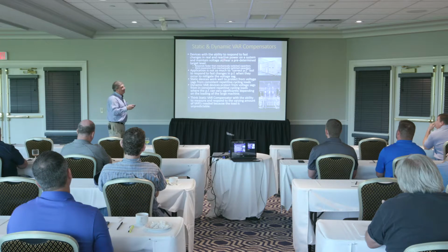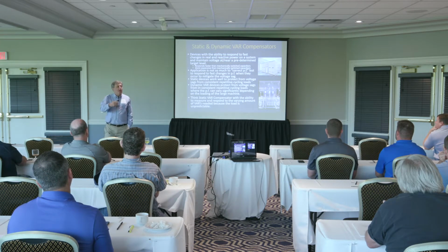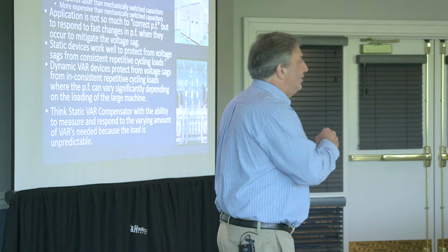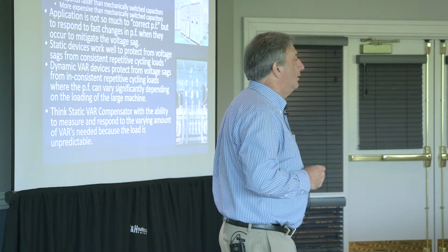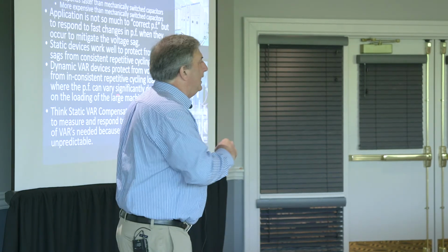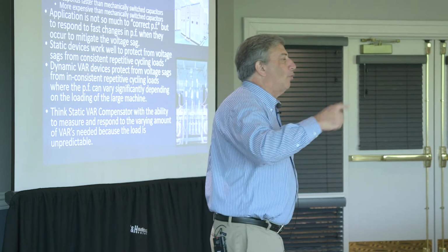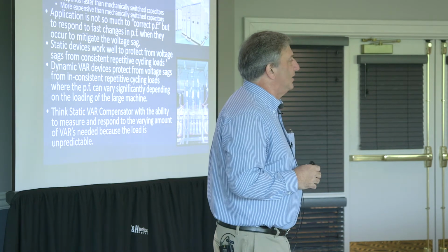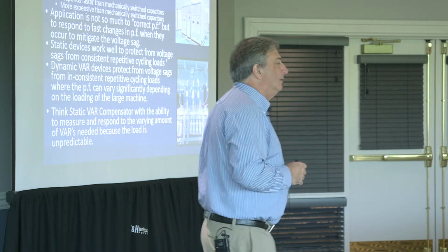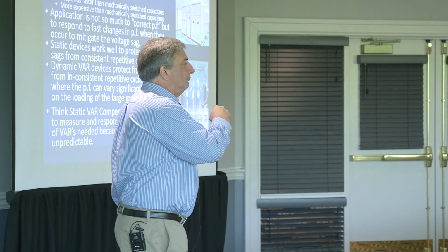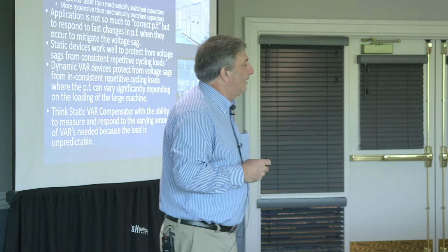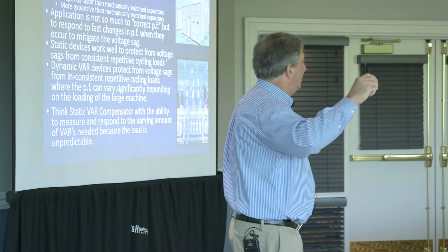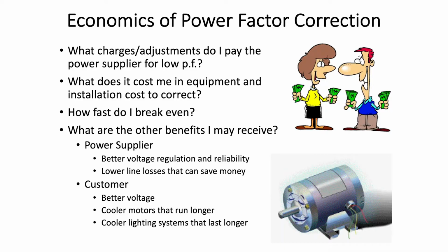So static and dynamic VAR compensators might be marketed to you if you're talking to a power factor correction consultant simply because they're more expensive and they do more. The only time you really need to look at these is if the power quality voltage sags that go along with some big motor starting in the system also need to be mitigated. So these will mitigate power factor. They act like power factor correction capacitors. They just do it faster and more precisely. They're more expensive. So the economics.